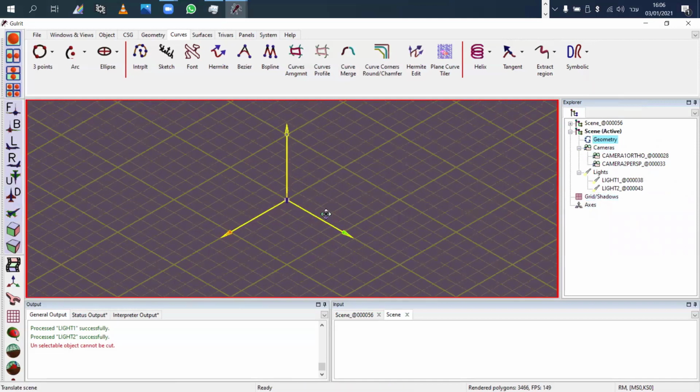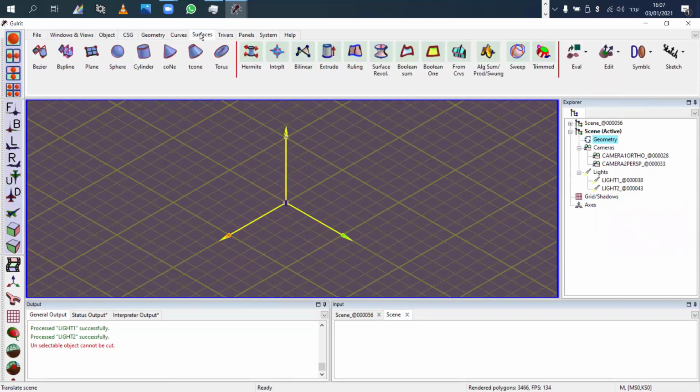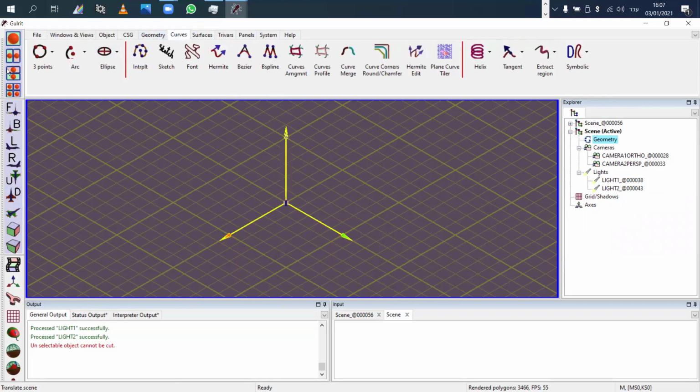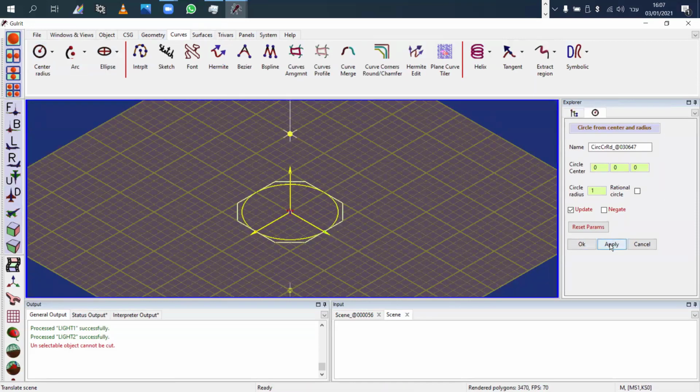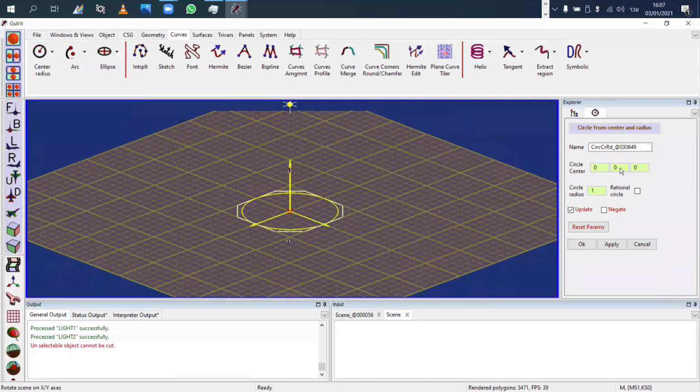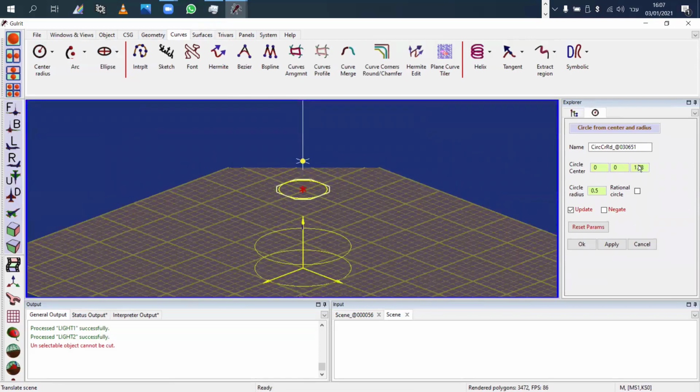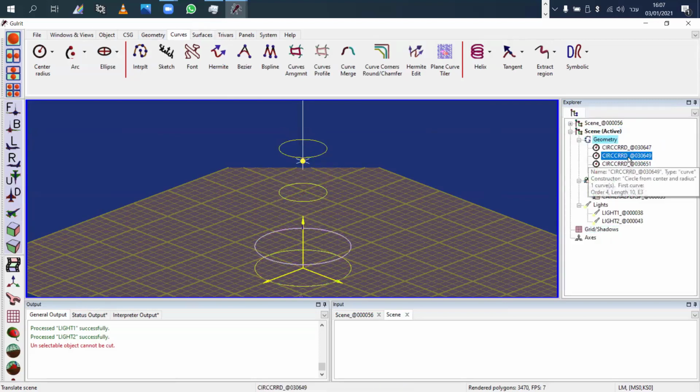And let's go directly into the surfaces menu. So in the surfaces menu, we can use curves that we created before. So let me just create some curves quickly, like I can create circles. I'm going to create this circle. Apply, again, apply, just commit and doesn't leave. I'm going to create another one over here, apply, and then make one smaller and make even a fourth one. Oops, I didn't apply here. And then a fourth one here. And I'm going to hide these three for now and use them later on.